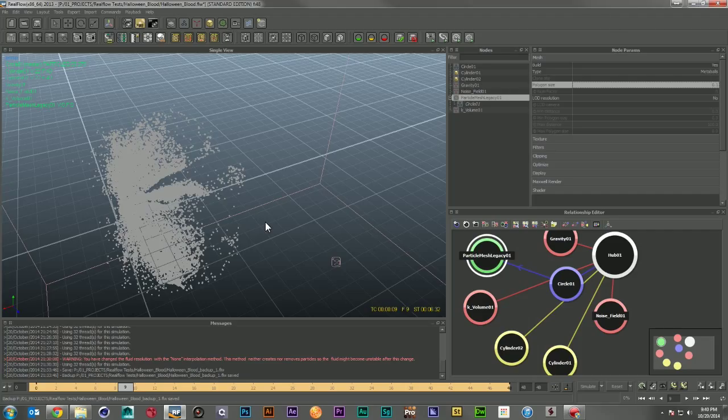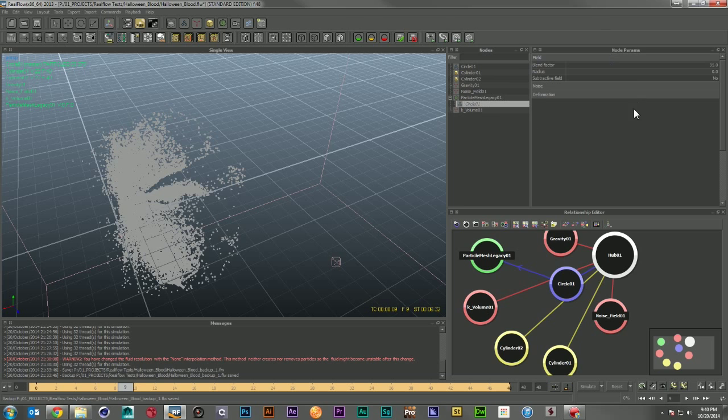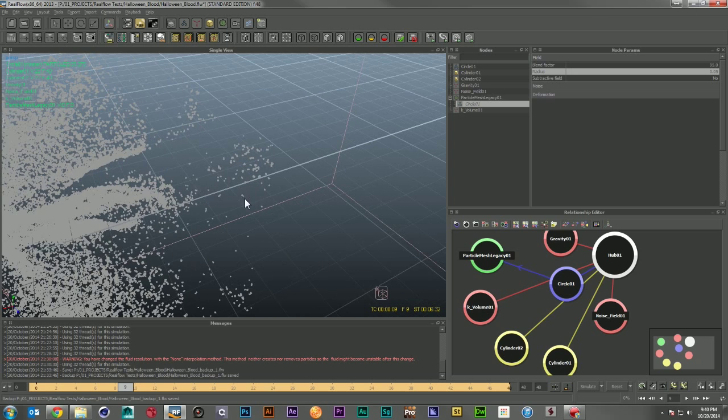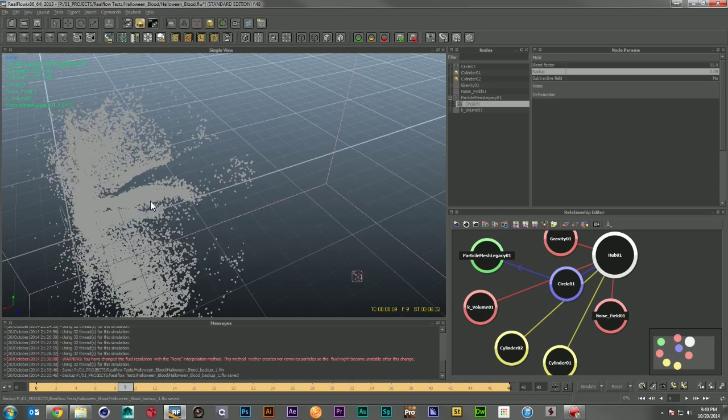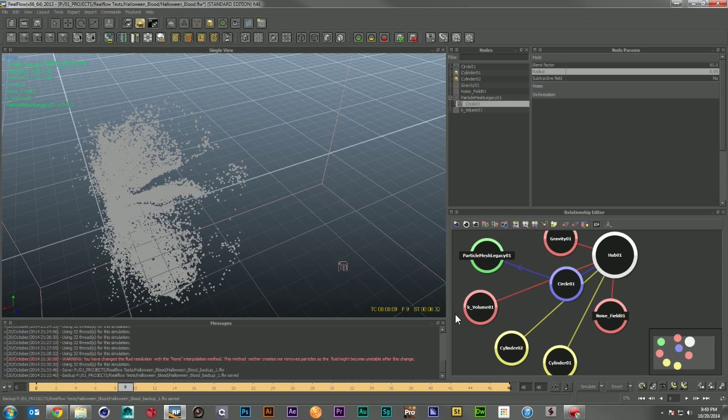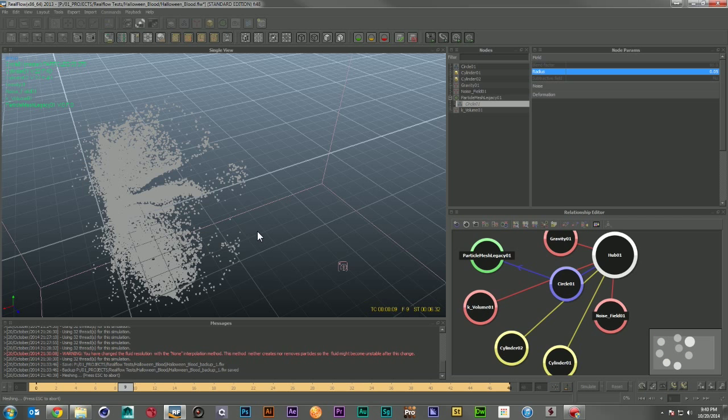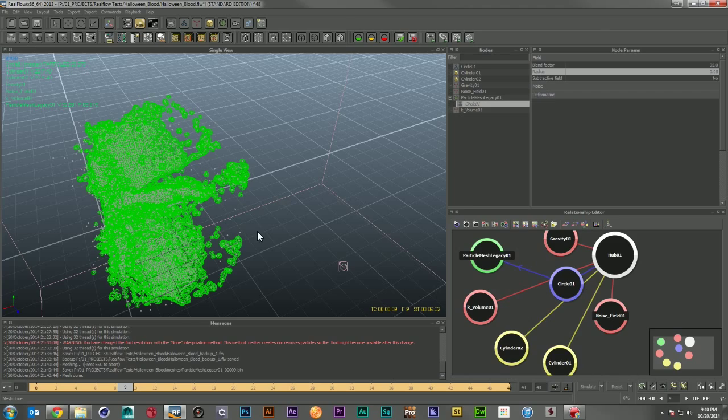If you're waiting a minute or two just to see whether or not your mesh is looking all right, you're really slowing yourself down. Then I'm going to click on my circle, go into the field, and give it a radius of maybe 0.05. I'm going to give it a very small radius. I don't want these little particles here to have enough attraction to pull the mesh way out here. I want the mesh to be very close to the particles. And I'm going to come down to the bottom and just click the Build Mesh button. Hopefully this will go pretty quick.